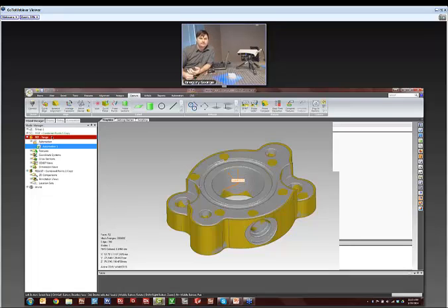So, good question here. It ties together a little bit about the 3D Systems culture itself. If we build a part in a 3D printer and then measure the part, would it be possible to create a new CAD file that is corrected? So building number 2, we will build with a changed CAD file from Geomagic Control that is changed optimally for better accuracy.